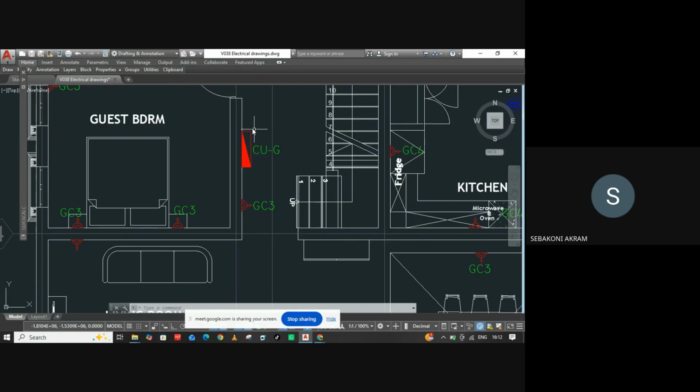So assuming this home was really a huge one, and in calculation of your load, you'd come to a maximum load of about 120 amps. For such a consumption, the most standard British breakers for single phase really go up to 100 amps preferably, but I see on the market they also produce those of 125, 120, but I don't expect much exceeding 120.